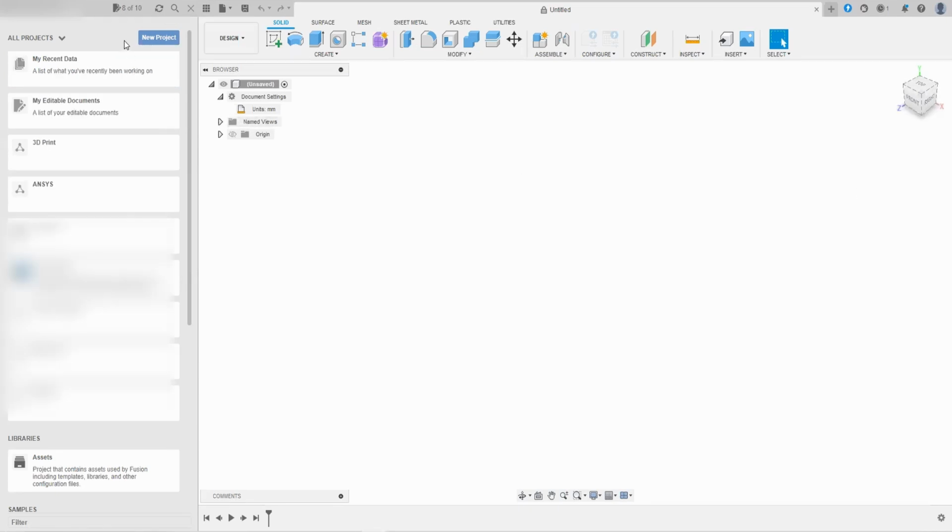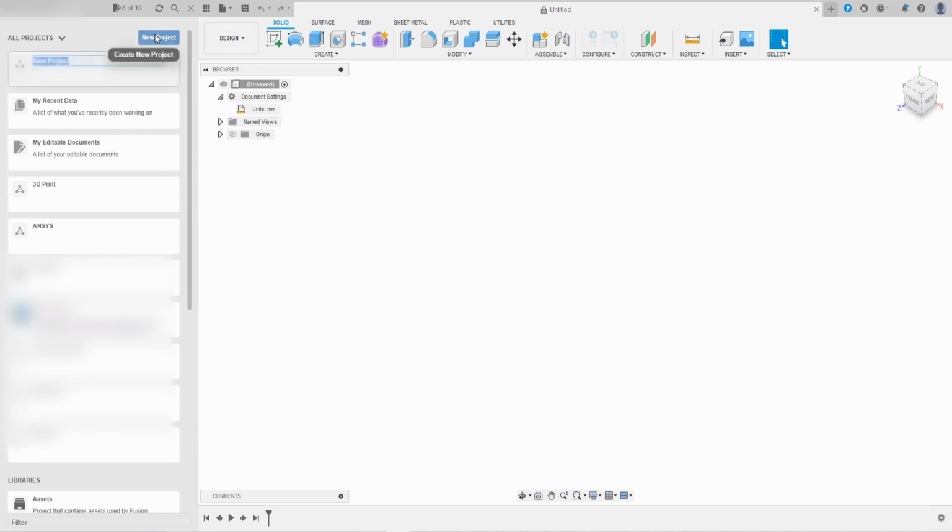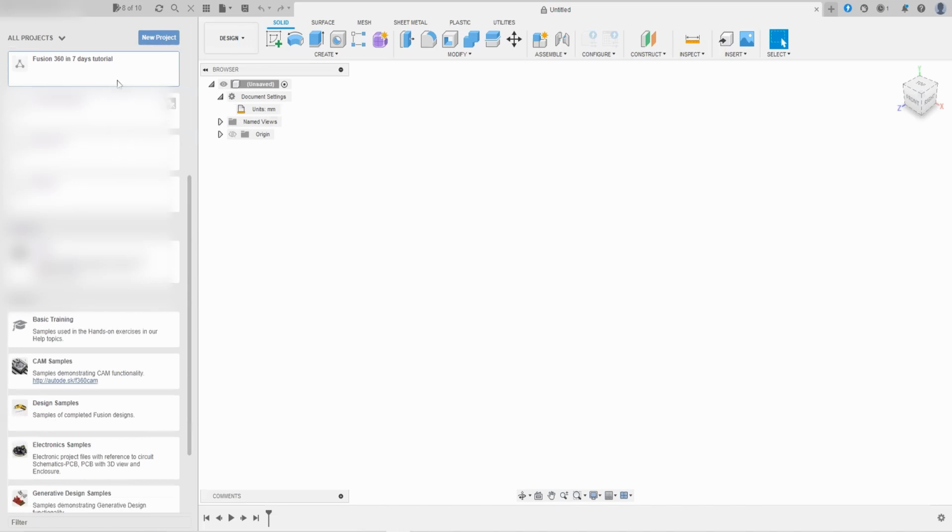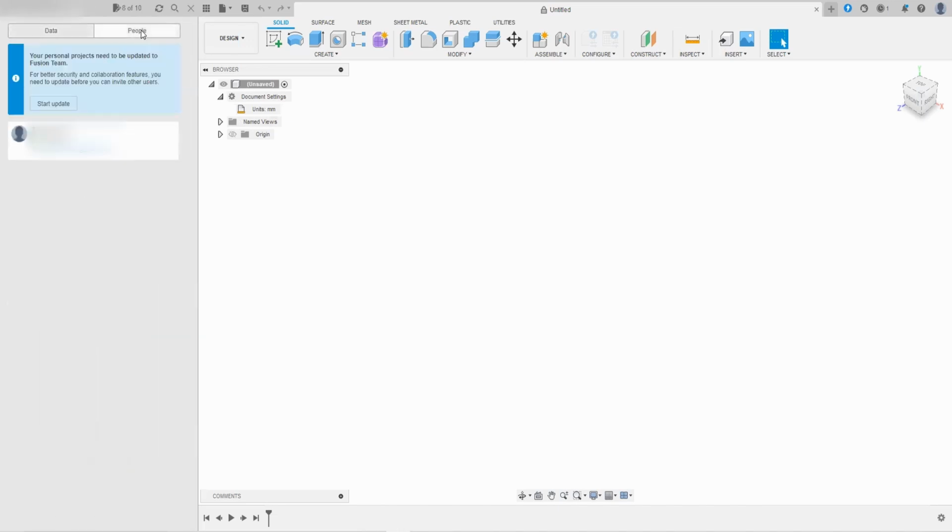So let's go ahead and create a new project for learning Fusion 360 in 7 days. Press on New Project, and let's name it Fusion 360 in 7 days tutorial. Double-click the project to open the folder. By pressing on the People tab, this is where you can add collaborators to your project simply by sending them an invite to their email that is linked to their Fusion 360 account. We can also add new folders within each project. So by using the New Folder button, we can create a new folder and call it Day 1. Now with our project folder created for Day 1, we can move on to creating our first object, the brick.